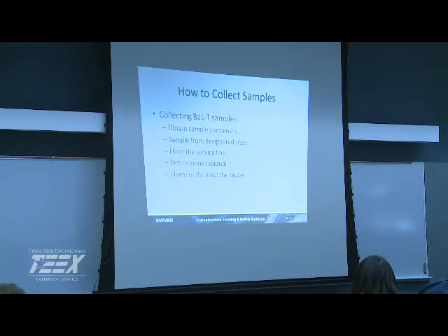But I love the fact that I can hit it with chlorine, and I know that I've taken care of it as long as I meet my concentration and my contact time. If I've got my CT squared away, then other than the Giardia and crypto, I've taken care of it really well. So we need to make sure we disinfect it properly, flush it real well.